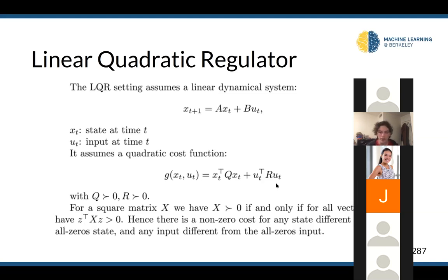And if you find out that actually the car is swerving around like a maniac, then you can change those constants to penalize steering more. So you sort of have to handpick this cost function to do what you want it to do, which is basically trying to better communicate what behavior you want. And if you can communicate that precisely by choosing what elements of the state and action we want to penalize, then it will find the optimal behavior. Does that answer your question? Does that make sense?